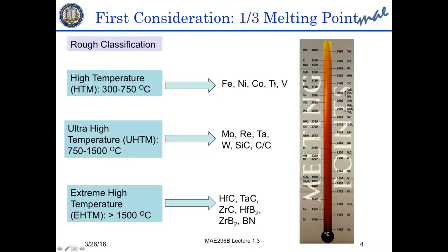Titanium is a hexagonal close-packed crystal structure. Vanadium is body center cubic. Cobalt is BCC. Nickel is face center cubic. Iron is body center cubic.